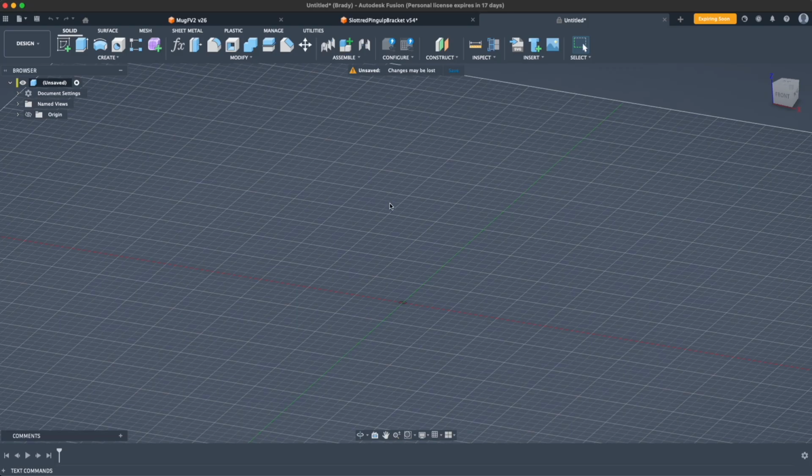But generally speaking, where Fusion really excels is with sketches and driving geometry based off those sketches in a parametric way, which means that you end up with a timeline that allows you to easily undo, alter, and change the state of your model. The problem with modeling in tools like Blender is, let's say that you wanted to change that mocha pot from an 8-sided polygon to a 6-sided polygon. It's extremely hard to do that. You would have to change the entire geometry. You'd have to manually manipulate the geometry or just start over. And that's one of the benefits of Fusion.